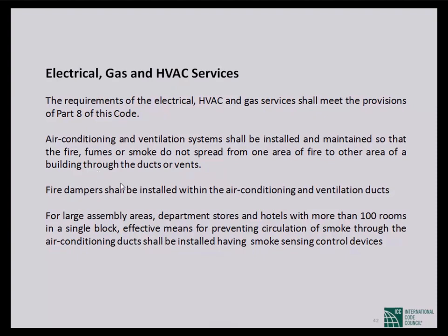Just one thing: the vent and duct for air conditioning and the vent and duct for smoke propagation, everything has to be controlled perfectly, because the same vent and same floor may be used by both. But you have to remember that when there is a fire, all HVAC systems will be off, but this vent, particularly the mechanical vent, must be on for removing smoke. So you have to be very careful while designing the vent for air conditioning and the vent for smoke and fumes at the time of fire.